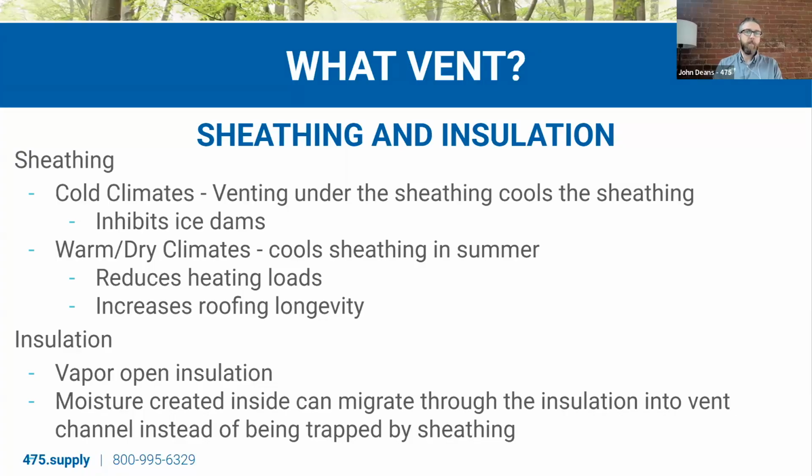We are ventilating the insulation. So again, we're allowing that insulation to dry, so it's not accumulating moisture, particularly vapor open insulation. So we're talking about cellulose and wood fiber, rock wool, fiberglass, open cell foam. So we're allowing those vapor open insulations to dry, to ventilate, and not be trapped by the sheathing.